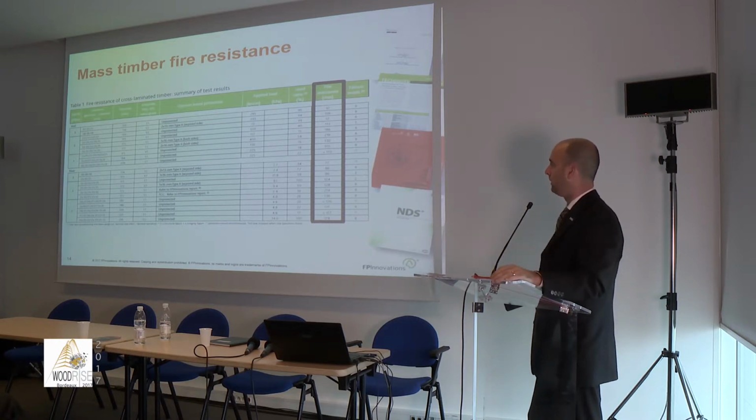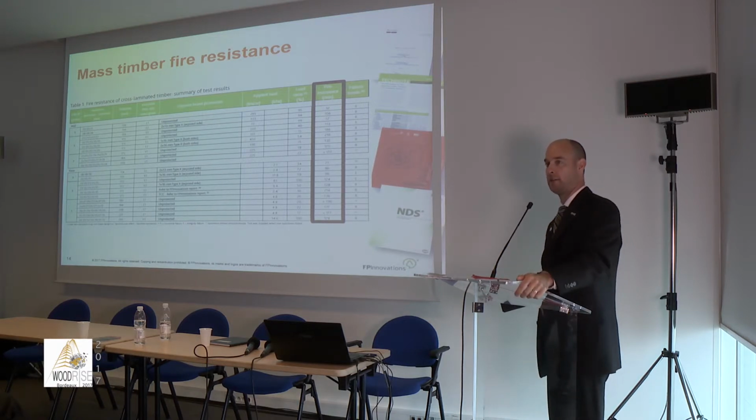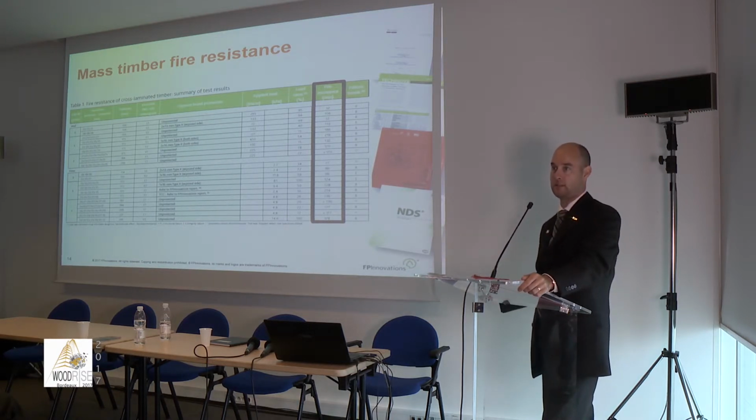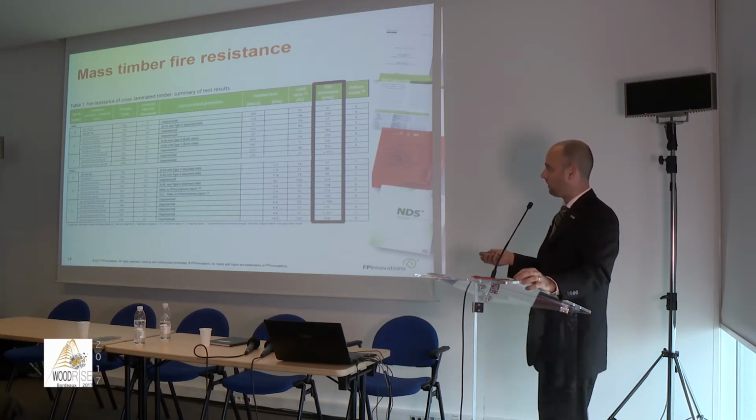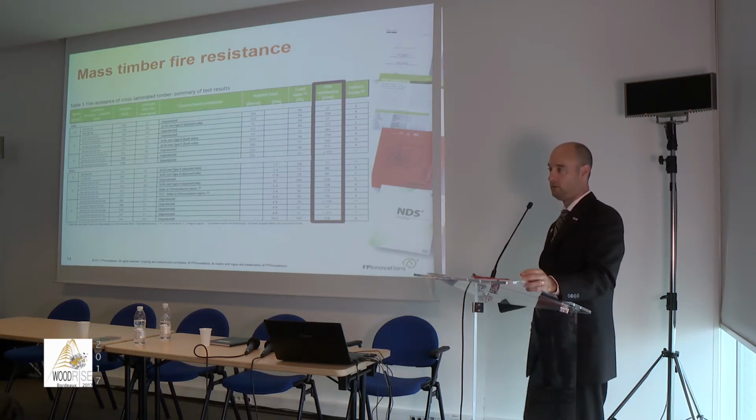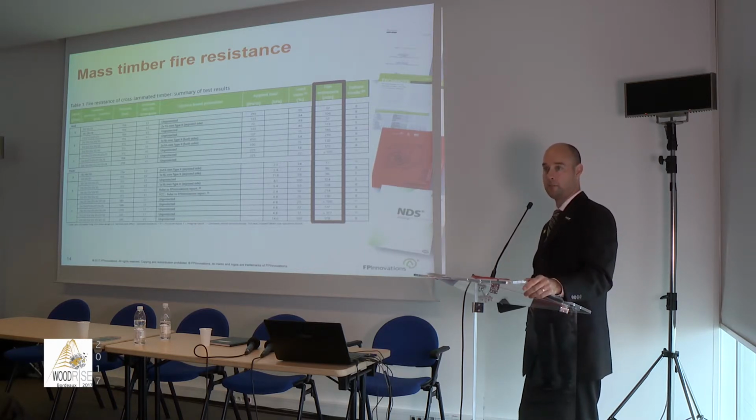What I'd like to show here is a summary of the CLT tests that we conducted in Canada. There are 20 tests that I'm showing here. There are different configurations, different thicknesses of laminations in the panel, different stress grades of CLT, and different loading levels, as well as whether sometimes the CLT is protected by gypsum board or not. Of these 20 tests, there are only 4 that are not beyond the 90-minute mark.